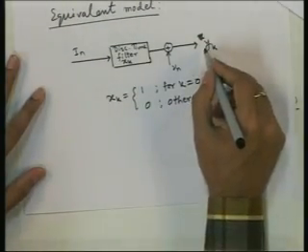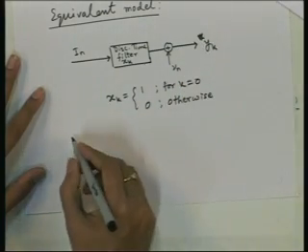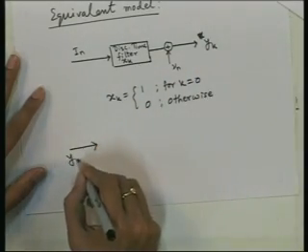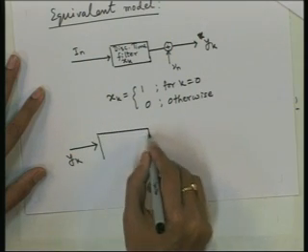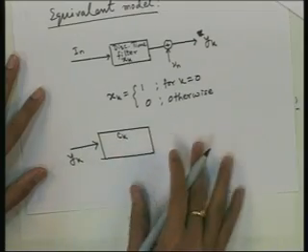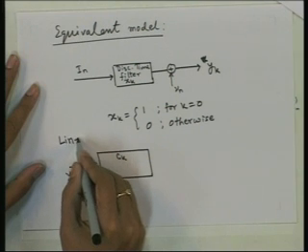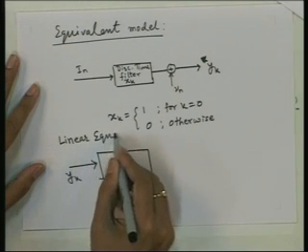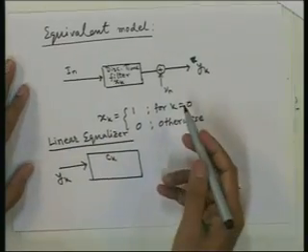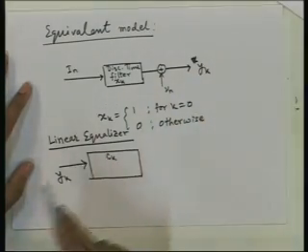So, in general we call a system through which this y k will be passed at the receiver, what we are considering now, a linear equalizer, where the way we try to recover I n from y k is by passing y k through a discrete time filter.